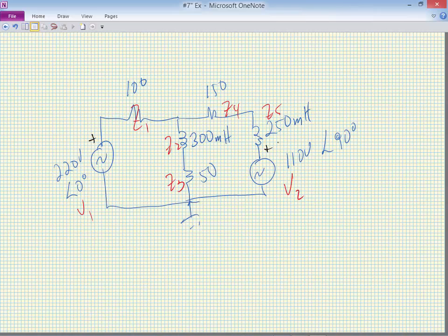Now, before I do that, let me just point out that XL, the impedance of an inductor, is j2πfL. Everyone, if being honest, has seen this before. Sometimes you'll see this written with omega. I don't know how they teach it here, but typically a technology instructor would probably use 2πf, and an engineering faculty member would probably use omega. They're both the same thing.